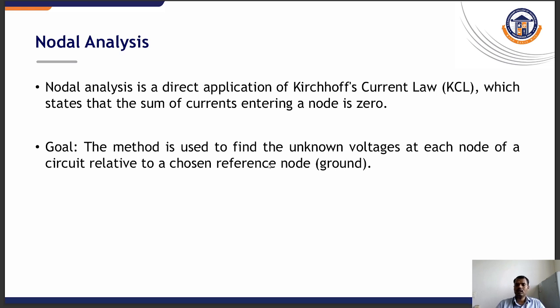The next is nodal analysis. It is a direct application of Kirchhoff's current law, which states that the sum of the currents entering a node is 0. So here our aim is to find the unknown voltages at each node of the circuit relative to the chosen reference node.